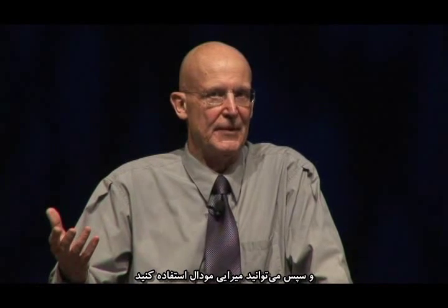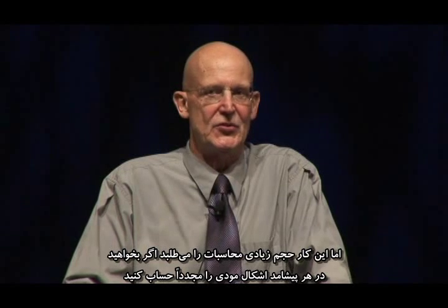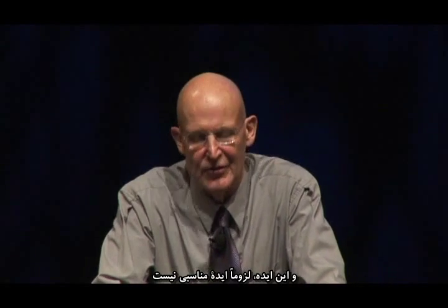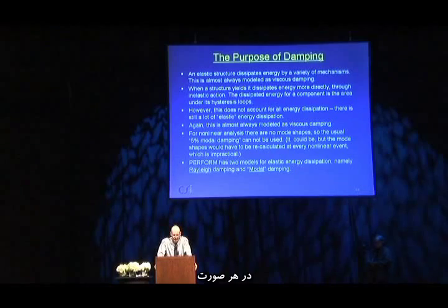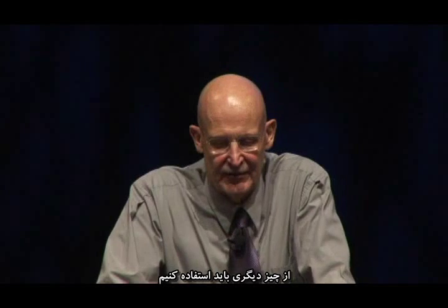Instantaneously you could say, well, there are some mode shapes, and theoretically at every change in stiffness, you could recalculate the mode shapes, and then you could use modal damping. But that's a hideous amount of computation if you had to recalculate the mode shapes at every event. It's absolutely prohibitive, so you simply can't do that. It's not necessarily a good idea anyway, quite apart from that. So we can't use the old 5% modal damping. We have to use something else.